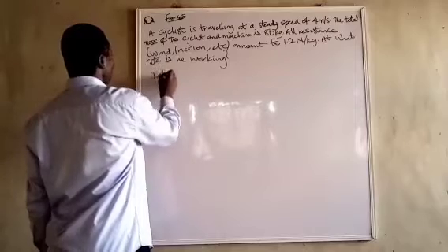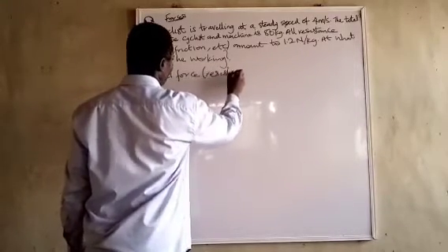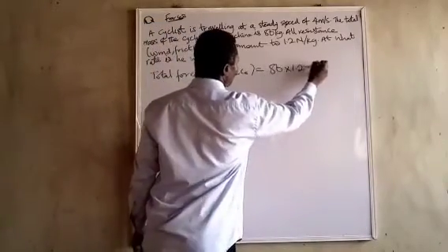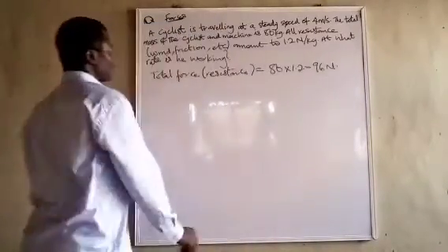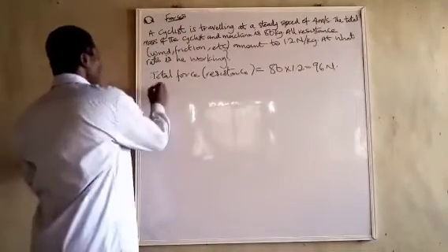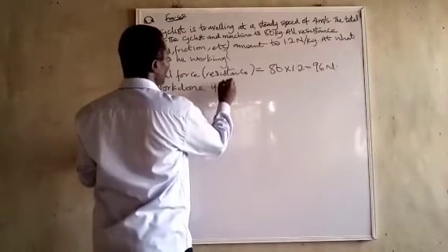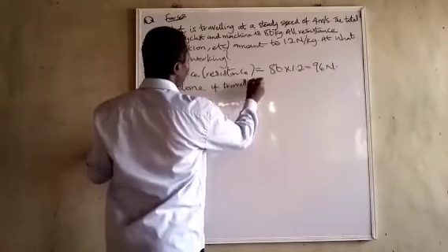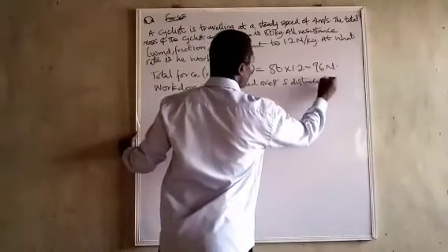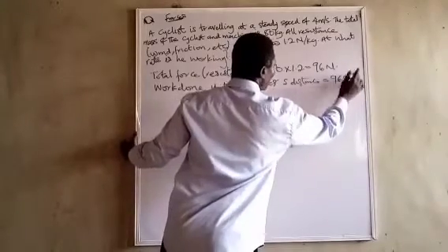So total resistance force is equal to 80 times 1.2, which is 96 Newton. And we realize that it is moving at 4 meters per second. So work done, if it travels over s distance, will equal 96 s Newton.